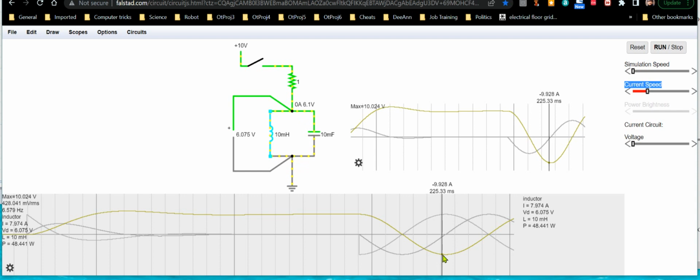But this is still the inductor charging up in reverse polarity, while the capacitor's current has become positive because it's actually supplying the current to the inductor in a particular direction. Because again, the current starts out like you see it right here, before I flip the switch.